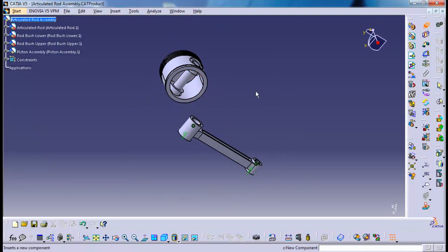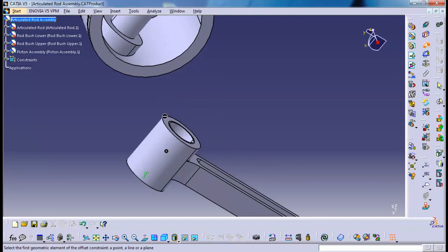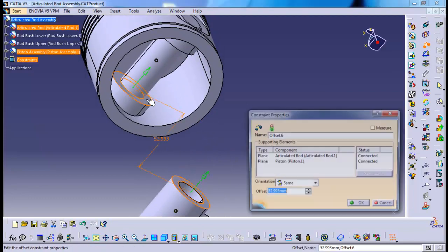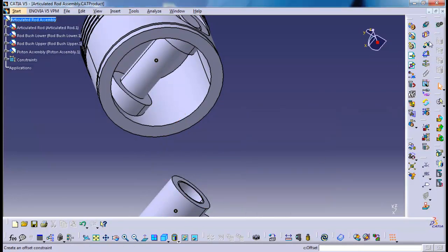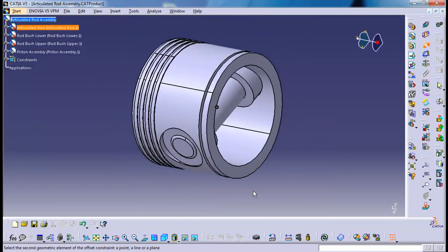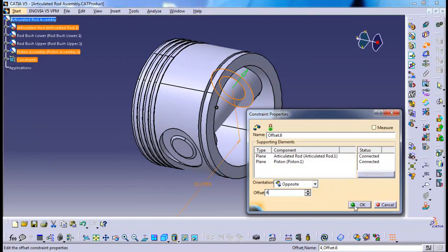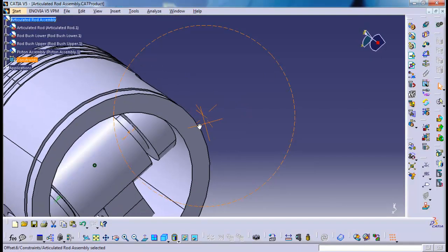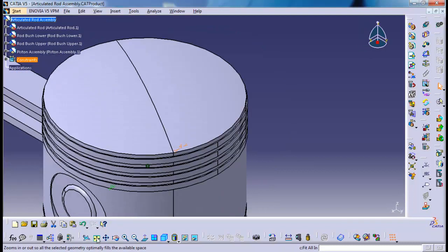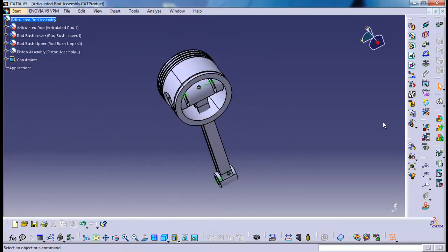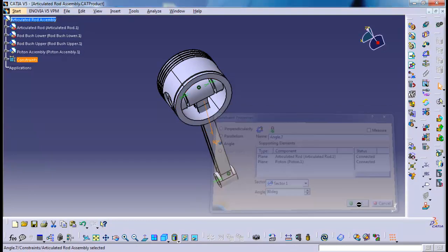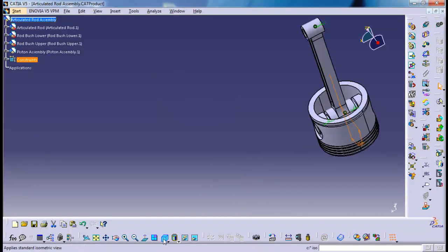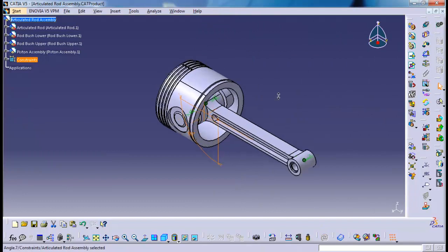It is obvious that this part also needs one more constraint now, an angular constraint, which is the first time we'll have used an angular constraint. Once this assembly is properly constrained, it would be good to also test this as we did the piston assembly by exploding and manipulating and updating to make sure it works.